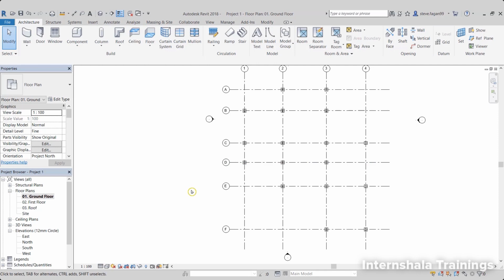So with the architectural columns, they're just a blank canvas. What that means is when we attach a wall to that architectural column, it takes on the properties of whatever wall abuts to that. So later on, we're going to draw our external wall around those columns. When we hit off it, it will automatically take on the properties. So it will turn into a block, plasterboard, brickwork, whatever we put to it. So it saves us time detailing around every single structural column in the project.